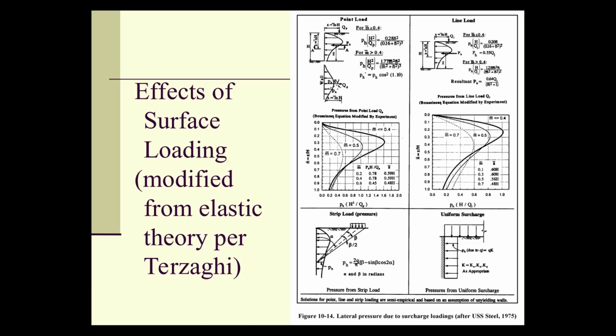The equations that we actually use are a little different, and they're shown in this. This is from your textbook, and they were modified by experiment, as Terzaghi noted in a well-known paper on anchored walls in the 1950s. Actually note that they're different. This also shows you the location of the resultant. It shows you that for different cases, actually, as the loads approach the wall, experimenters modified the